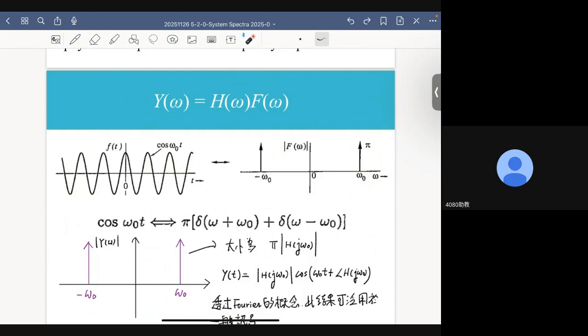We introduce the concept of a complex variable, and at the same time, the signals are all real, functions of real numbers. So this negative frequency is just a mathematical byproduct. There isn't any real physical entity that corresponds to this component. And that is the reason why, as we have discussed many times, the amplitude spectrum is always an even function of frequency.